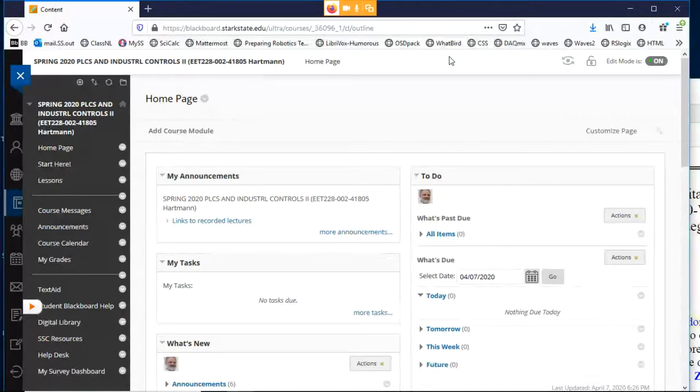Okay. Matt, I just saw your question about the autosave. Yeah, I guess I haven't tested any kind of autosave, but I've noticed with this software that if you don't accept those rung edits and you try to do an undo, it undoes the entire rung. It wipes out, you may have done 3 or 4 different things on that rung, and it wipes them all out. So I recommend clicking that accept changes quite often.